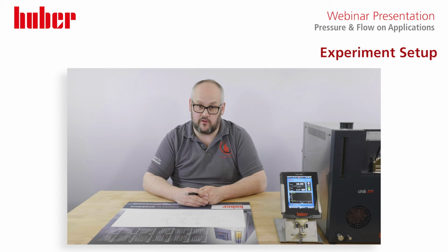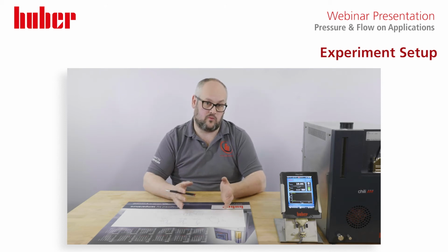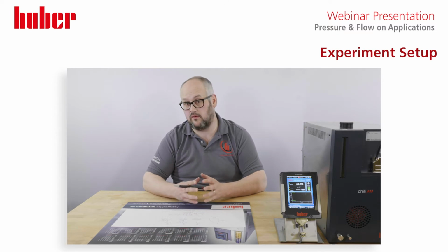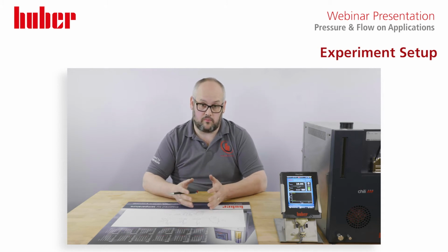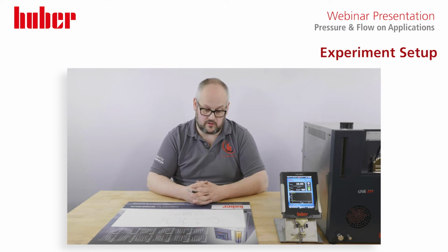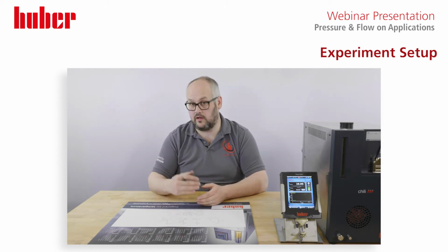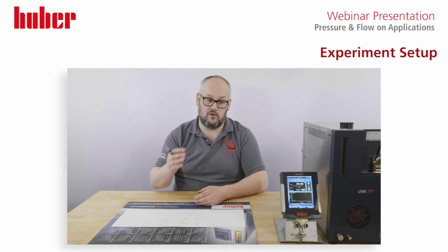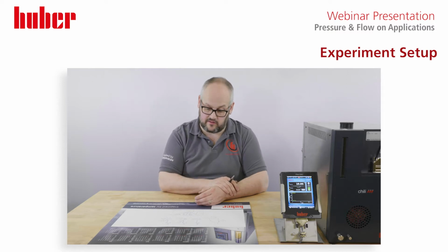In our Unistat family of products, we do have an inbuilt pressure sensor as well as our pump. However, in certain Unistats, we have fixed speed pumps, whereas other Unistats have what we call a VPC pump, which is a variable pressure control pump. Utilizing this pump, we can actually go down to 500 RPM up to 3500 RPM and adjust our speed in relation to pressure. So when you slow it down, you get a reduction in pump speed, or you get a reduction in pressure. However, you cannot go to absolute zero. Some applications require absolute zero. We'll bring them up in a minute when we talk about an externally mounted VPC.